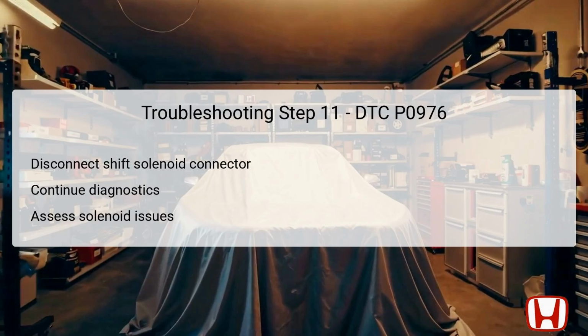This could include checking for voltage at the connector or testing the solenoid resistance directly. Each aspect of this diagnostic process is crucial to determining the root cause of DTC P0976 and ensuring the shift solenoid valve B operates effectively within the transmission system.